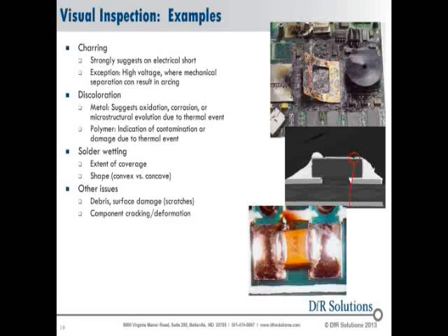And it's also good to look for any kind of cracking or deformation, like if there was a heat event that twisted and warped something, or you could have also had conformal coatings or solder mask or some of the features that are designed to keep moisture out cracking and flaking and peeling away, making the design more susceptible to moisture and humidity attack.